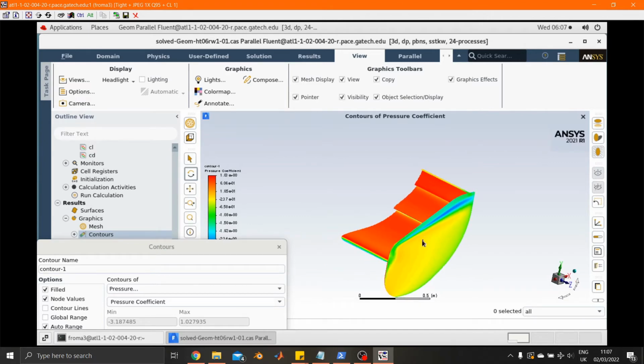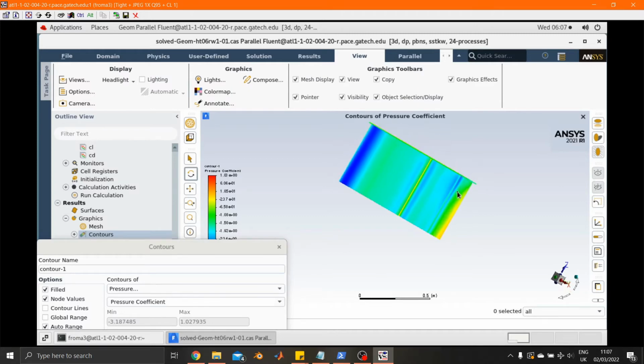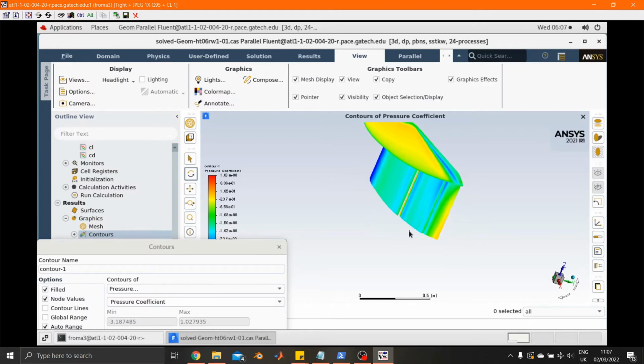So you can see the top, all of it is red, and the bottom you'll see is blue. And this view right here is really helpful in seeing where on the rear wing you're gaining or losing performance, right? So you can see the edge closer to the end plate actually has more negative pressure, therefore it's producing more downforce than the middle, where the flow is being separated a bit right up here, where the third element is. So that'll tell you that you may want to back off the wing in the middle, or may tell you that you want to reduce gurney flap in the middle, maybe reduce the whole gurney flap as a whole. You may want to have some sort of swept profile for the wing, which gets quite complicated.